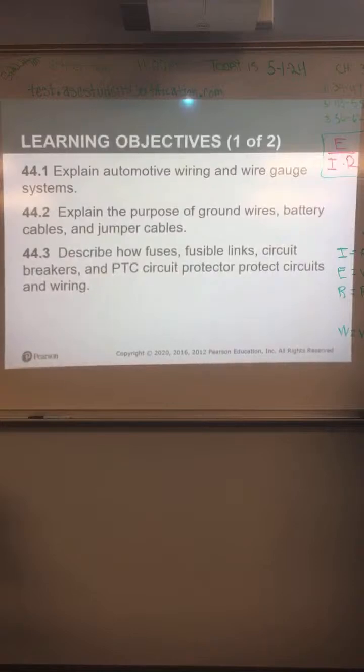Tech A says that position allows both AC and DC signals. Tech B says this setting allows just DC waveform to be displayed. On DC coupling, it's just A, I believe, so 6 should be A. 7 we did, 8 we did, 9 we did, and 10 we did.